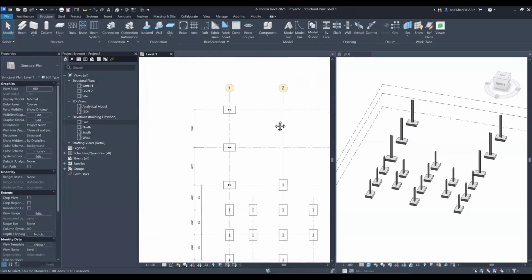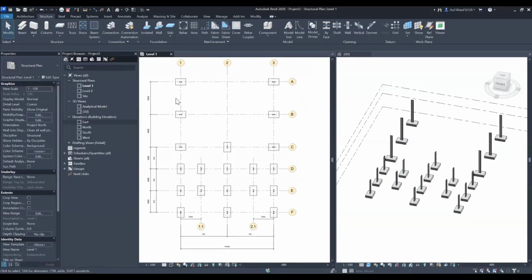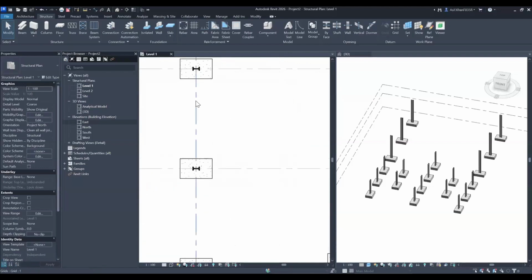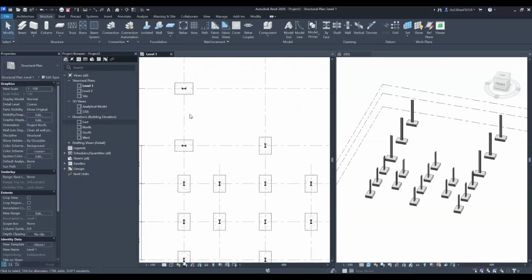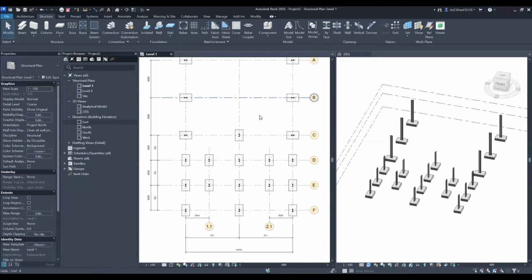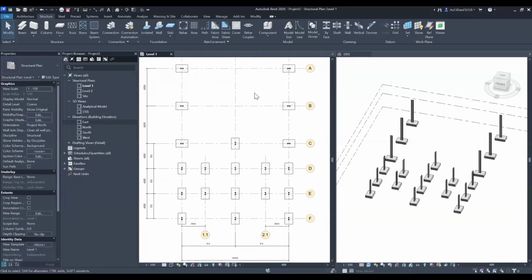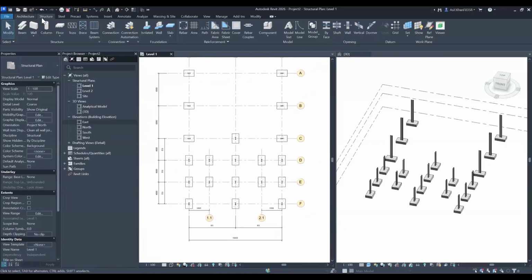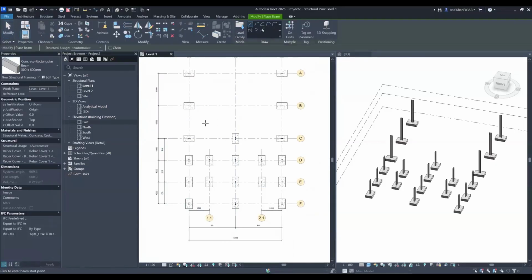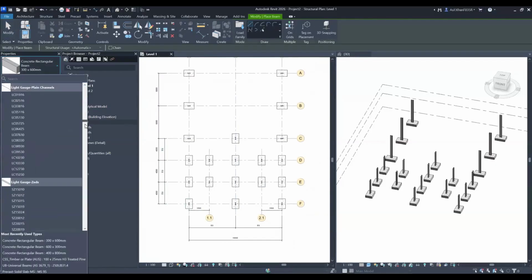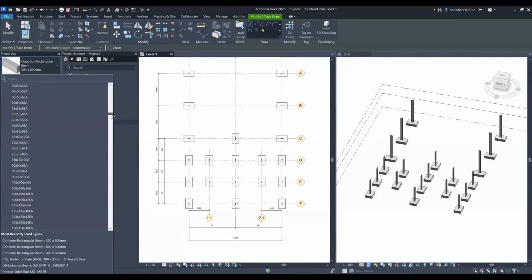All right, let's say we're going to put some foundation beams connecting these columns. Now, if you go back in memory, how do you do it? We'll be offsetting this grid on both sides, then trimming at the column and foundation location, and keep doing this all over the place, which is a very time-consuming process. Honestly speaking, I have also done that. Now, if I take my beam tool from my structure tab, I'll be given a choice of lots of beams. As I said, already loaded, so don't worry.